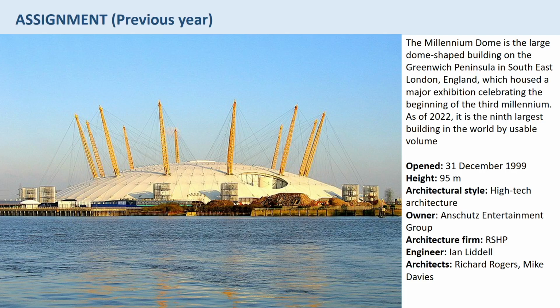Pneumatic structures. A pneumatic structure is a membrane structure that is stabilized by the pressure of compressed air. Pneumatic structures are characterized by slightly higher pressure of internal air above the outside pressure. These structures are supported by pressurized air within the inflated building elements that are shaped to carry the loads in a traditional manner. The roof membrane of the pneumatic structure is made from rubber or reinforced films using industrial fabrics coated with polymers.